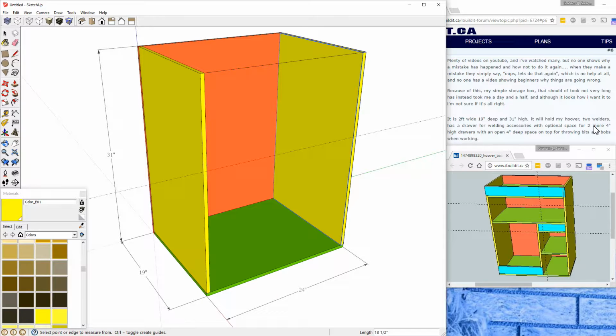So if it's a 4-inch space and I started from the bottom and the plywood at the bottom is 1/2 inch thick, then I actually need that guideline to be 4.5 inches from the base. Again, I'm going from the measurements in the text. I think that the actual diagram is a different scale, but we'll carry on with that.